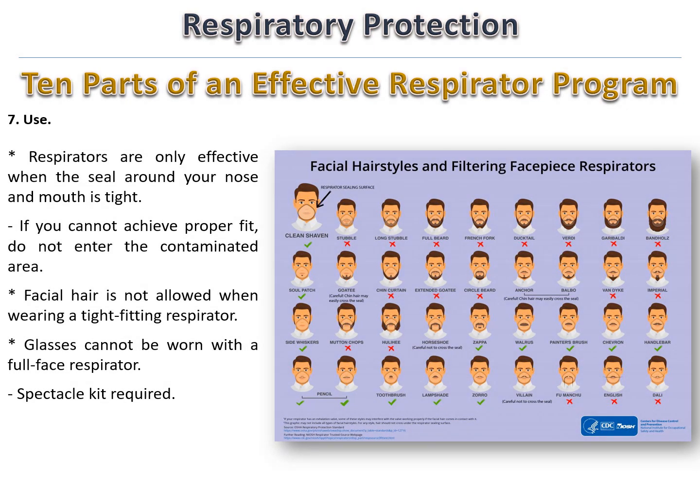7. Use. Respirators are only effective when the seal around your nose and mouth is tight. If you cannot achieve proper fit, do not enter the contaminated area. Facial hair is not allowed when wearing a tight-fitting respirator. Glasses cannot be worn with a full-face respirator. Spectacle kit required.